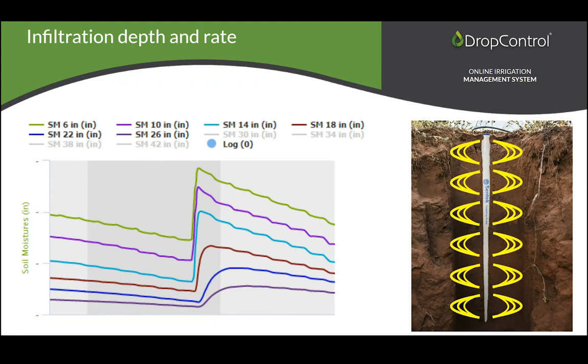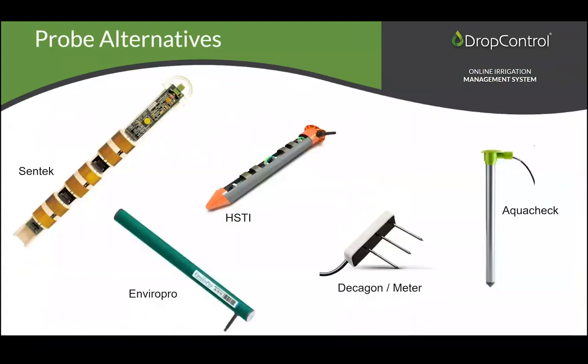So that is something to absolutely keep an eye on when you're choosing a probe and when you're installing it. And if you do choose a probe with a lower area of influence that needs to be installed with a slurry, then you need to keep an eye on those readings for the first few weeks. Gotcha.